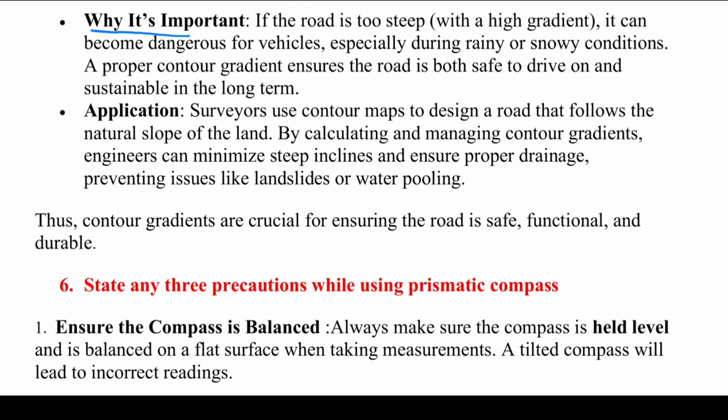In a steep hilly area, if we consider a high gradient, it can be dangerous for vehicles, especially in rainy and snow conditions, if the gradient is very steep. So we have to take a proper contour gradient, for the safety of the driver and the safety of the road, and suitable for the long term. That is one of the important points.